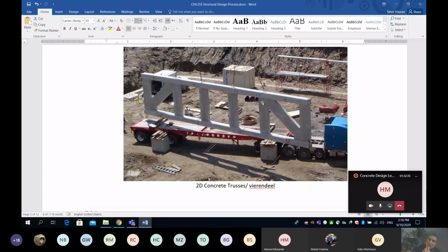Because it's not webbed. You're very close. But what do you mean webbed? Like the structure in between the 2 beams doesn't look like a regular truss. Only the 2 sides look like it could potentially be webbed, but there seem to be posts in the middle. There's no gussets. That's concrete. There's no gusset at all.